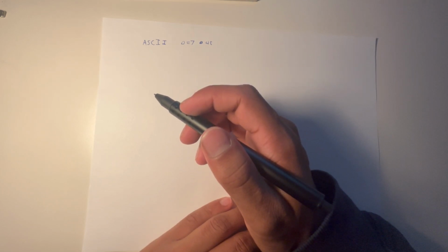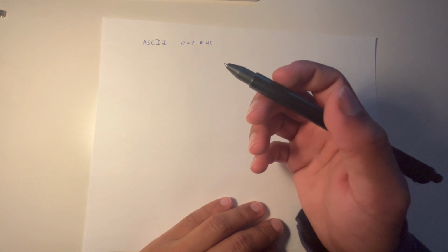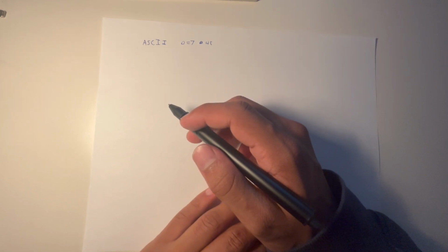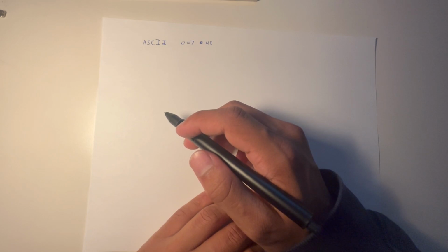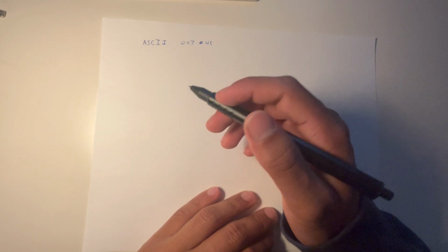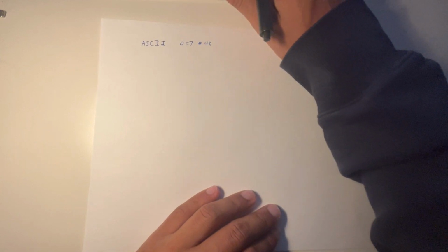And so to do this, we arrive at the good part of the project, the shift and add 3 algorithm, otherwise known as Dabble. The shift and add 3 algorithm is exactly what it sounds like. Everything is shifted left, and you add 3 to a nibble when it's 5 or more. So very quickly, let's run through a sample conversion.